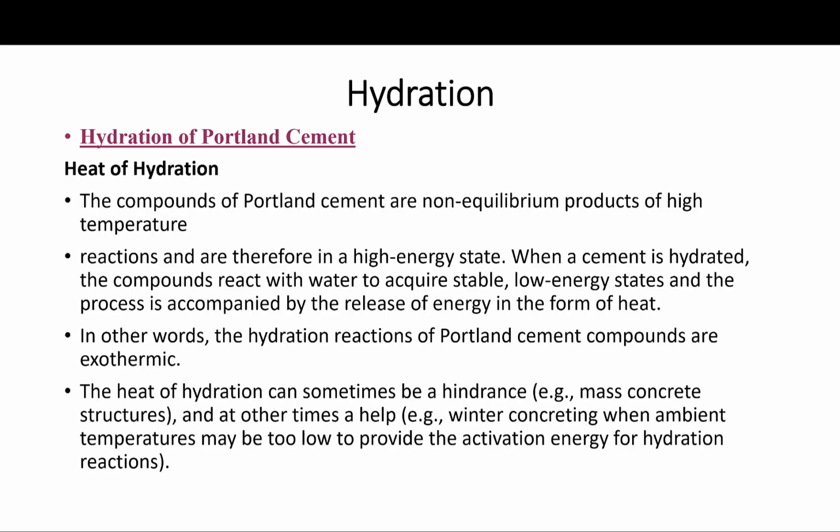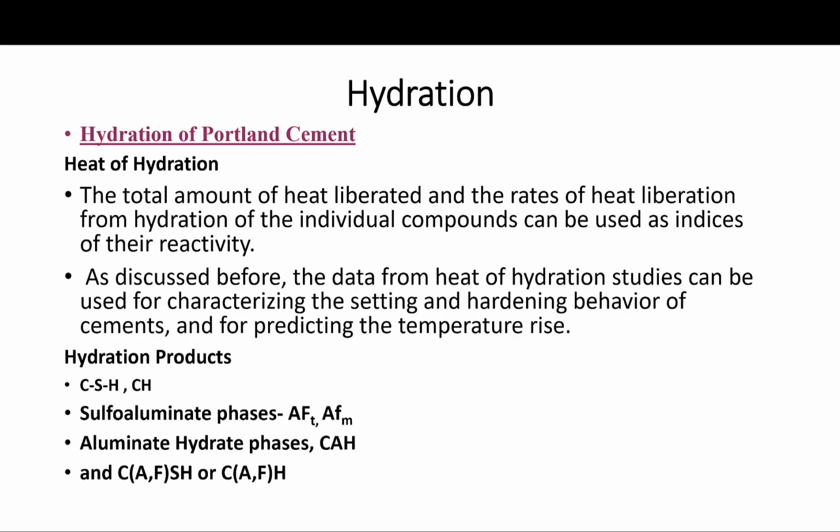So the heat of hydration can sometimes be a hindrance, if you remember, especially when we are dealing with mass concrete structures or sections. And other times it may help, especially in winter concreting, or when ambient temperatures may be too low to provide the activation energy for the hydration reactions.